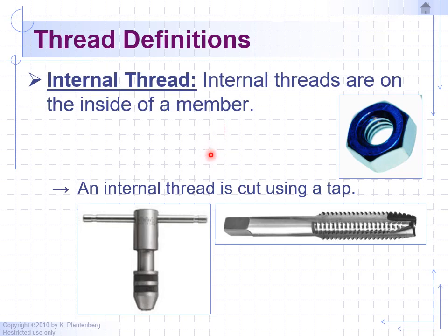First you drill the holes. Obviously you're going to drill a smaller diameter hole. Then you come in with these manually, or you can do it on a 3-axis machine where it'll come in with this tap tool, and it'll slowly turn to create the threads. You don't want to go too fast, or you can end up breaking this tool.